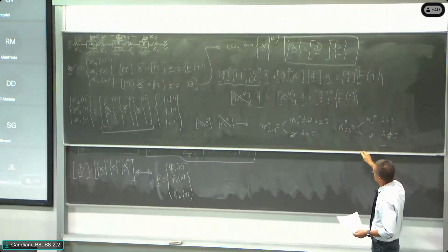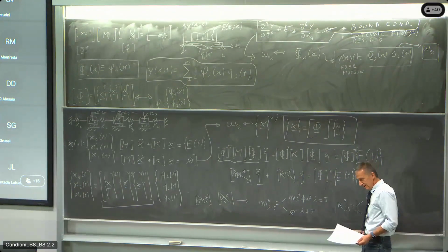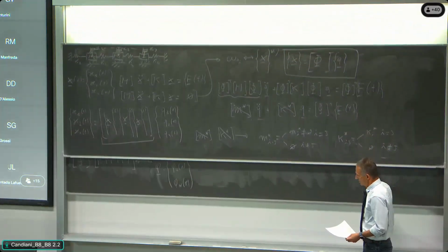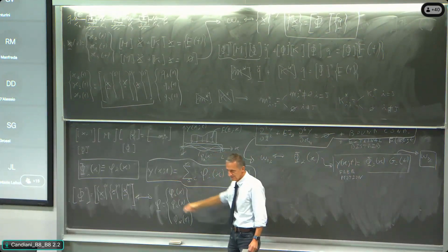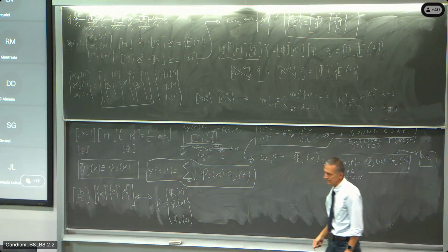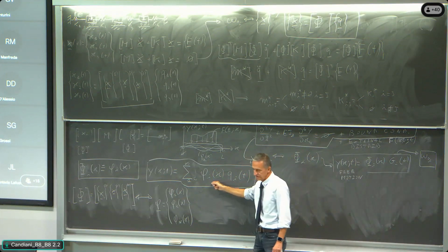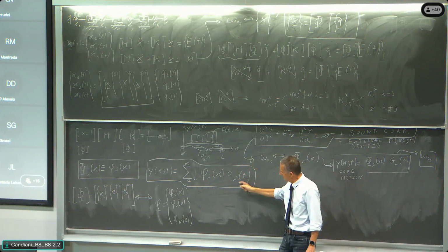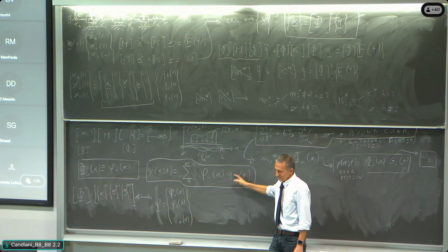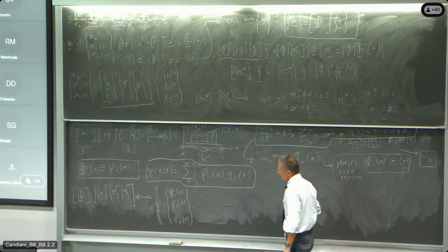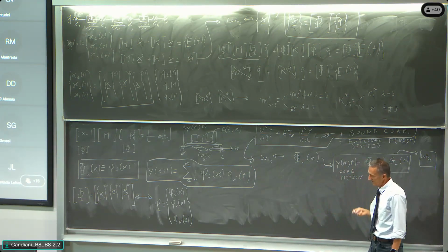And so the definition of the transformation of coordinate X equal to something is made now saying that we can represent whatever movement of the continuum through a linear combination of the modal shapes, multiply each of them by a function of time. What we have to understand is the meaning of what we are writing here.